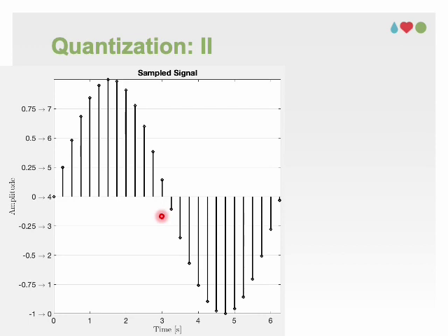For a 3-bit ADC, we have 8 levels, as shown in the previous slide. The 8 levels are labeled by decimal integer values of 0, 1, 2, 3, 4, 5, 6, 7, as shown here. It means we map from amplitude to a finite number of integers, in this case 8 values from 0 to 7. This is our first mapping, as shown here.